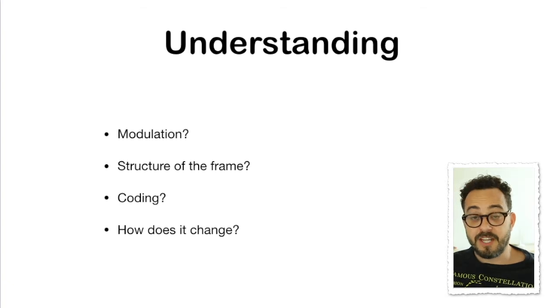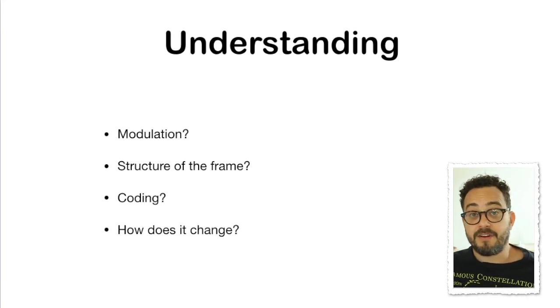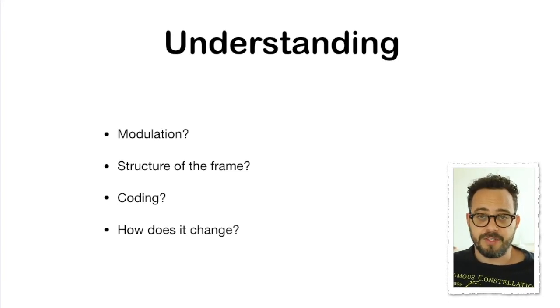We want to understand what is its modulation, what is the structure of the frame, if it's coded somehow, and how does it change when the packet itself changes. So in that case, we will see how it changes when we press different keys on the remote control to see if there are changes and where these changes are occurring.